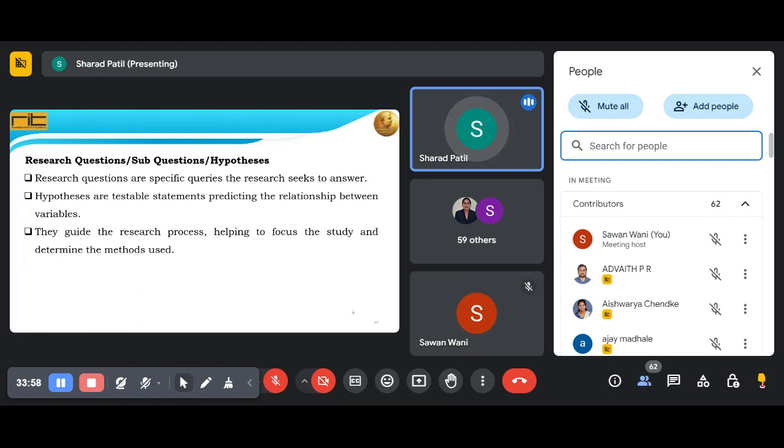So this is the hypothesis, and as you know, if conductivity is more, definitely, as per the law, suppose as per Fourier's law, Q is equal to minus K dT by dx, or as per Newton's law, Q is equal to h A delta T. If the heat transfer coefficient h is improved, definitely heat transfer will improve, or if K in minus K dT by dx is improved, there will be improvement in the heat transfer. So here we have a relationship between the different variables. If I want to improve the heat transfer by Fourier's law, I can change the K, I can change the delta T, so that definitely there will be some improvement in the heat transfer.